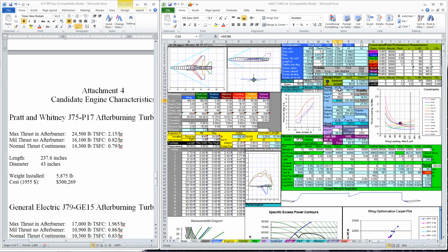We gained a little weight when we added the vertical tail, and the vertical tail is probably just a little bit too far back. Let's try 43. I was afraid of that. Let's try increasing its aspect ratio. That makes it a more effective lifting surface. When it had that horizontal tail on top of it, a lower aspect ratio tail was a good idea, because you've got all those loads out there. You don't want to have a heavy structure to hold a long, slender vertical tail. But now that the horizontal tail is firmly mounted on the fuselage, we can have a higher aspect ratio horizontal tail. And that's to our benefit.